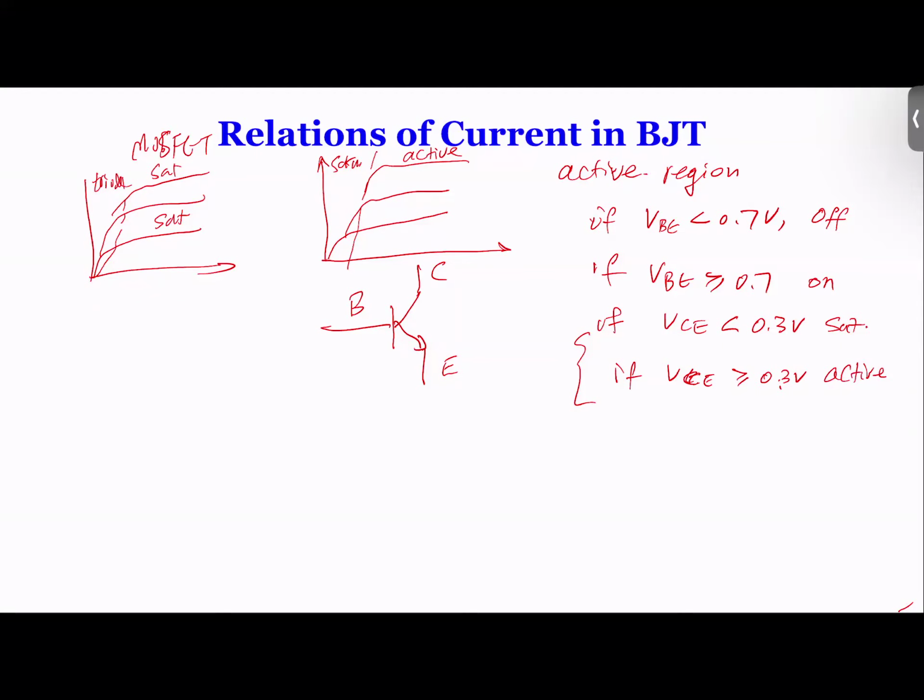In the diagram, VCE is roughly 0.3 volts if you look at this region here, if you follow my writing. Between the origin of the coordinates all the way to where the current becomes flat, that region is called the saturation region, and the voltage between collector and emitter is about 0.3 volts. Mostly, we're going to look at the active region when we move on to amplifiers.